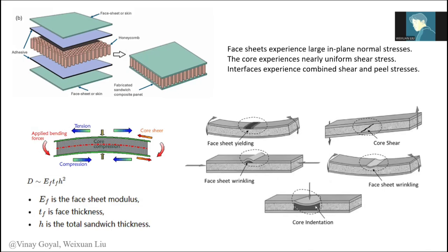If we want to even proceed to a debonding analysis, then we want to introduce the cohesive element between face sheet and core and introduce damage initiation and evolution. And in that sense, mesh considerations are important because there will be high stress and deformation that cause shear locking. The core nonlinearity can affect convergence, and the softening behavior because of the plasticity will require other stabilization processes.